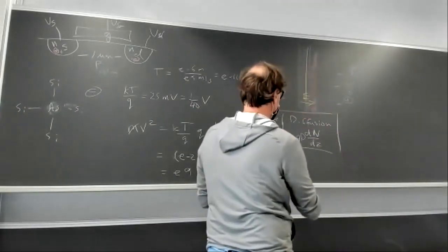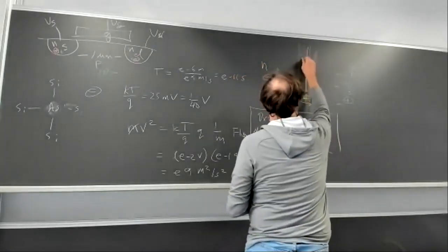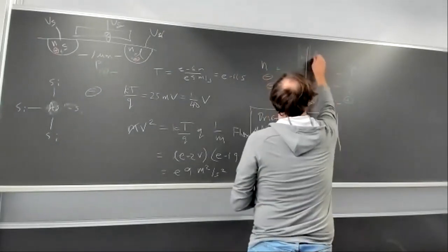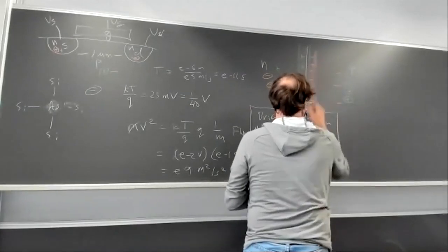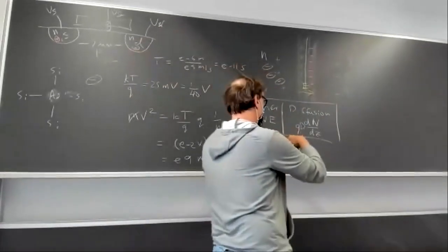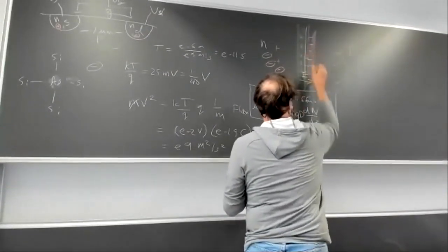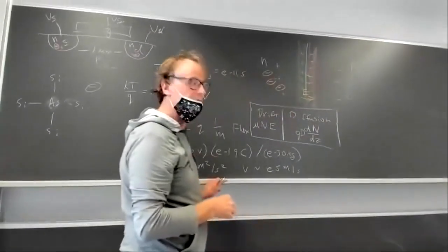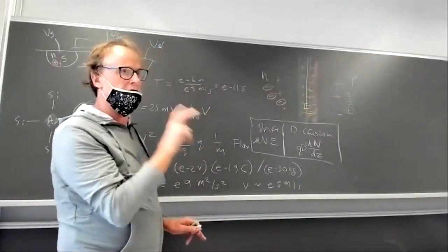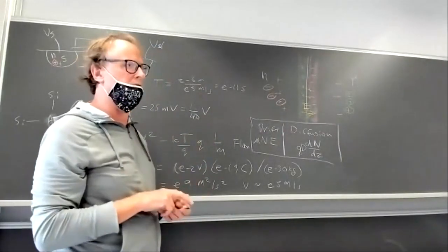So right in this depletion region, this so-called space charge region, the bare charges are exposed. Let's see how this works out. We want an electric field pointing from there to there, so we're going to have pluses here, fixed ions, and I'll make the electric field point to the right. Every time you have a pair of such fixed ions, you get a little field line connecting them. It points from the plus to the minus. Inside that space charge region, there's this huge electric field, millions of volts per centimeter, or at least hundreds of thousands of volts per centimeter.